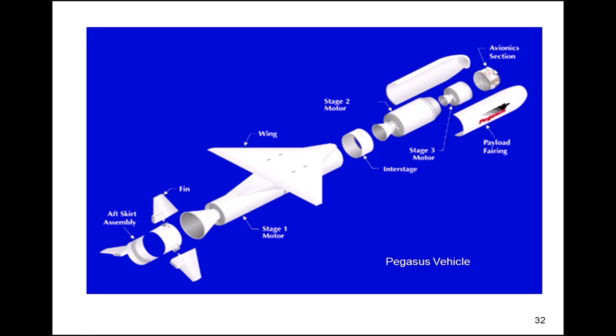Now there's also an inertial navigation system in this avionics section, and that has 3 translational accelerometers and 3 gyroscopes. And that data is taken, and there's various coordinate transformations performed and integrations. And based on that data, there's a software in the navigation system that can determine where this vehicle is as a point mass. In other words, where is the CG of the vehicle in space at any given point in time. And also that same software can determine what the attitude of the vehicle is.